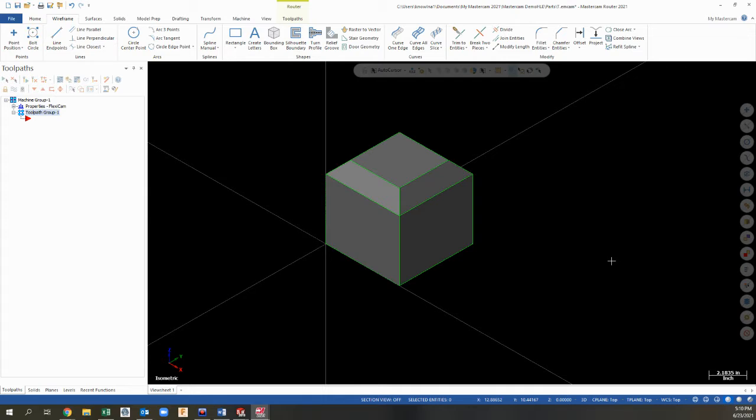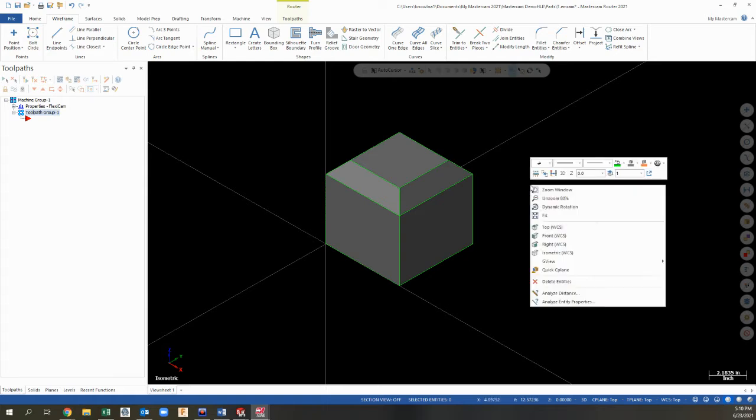The 3 standard views, which you will find on almost any drawing. If we access right click, go to our quick view, these are views. They also correlate to planes. So top view, front view, right side, ISO, or we have the remaining views that we can choose from.